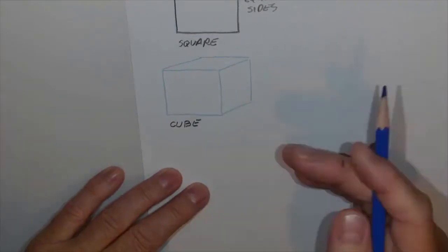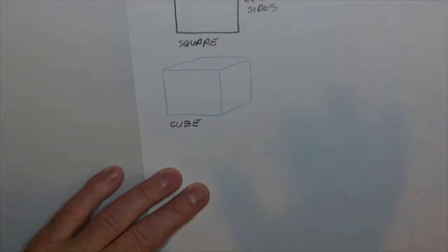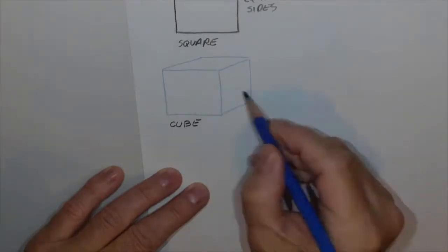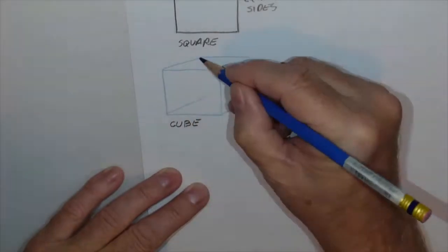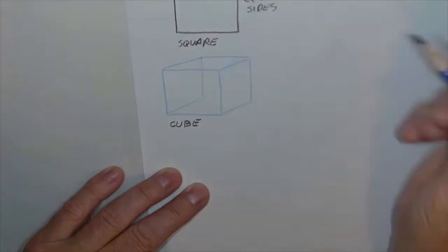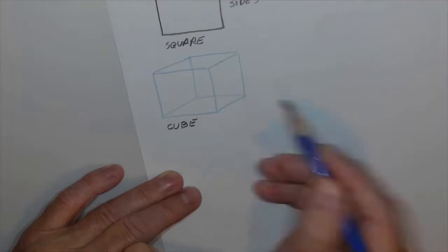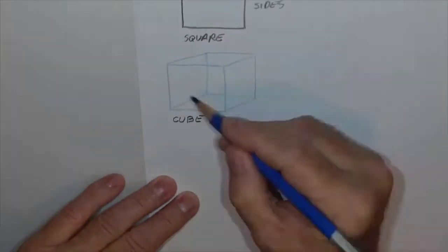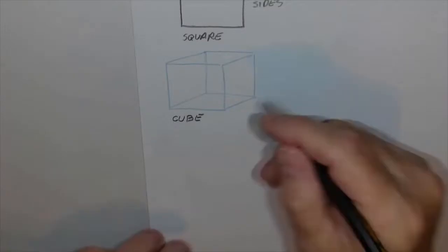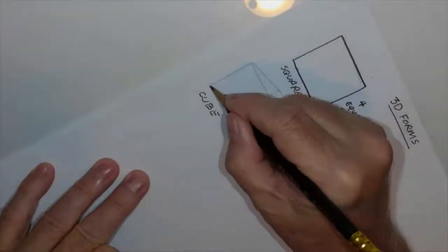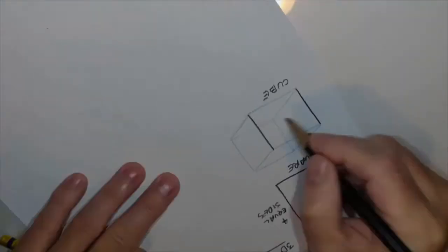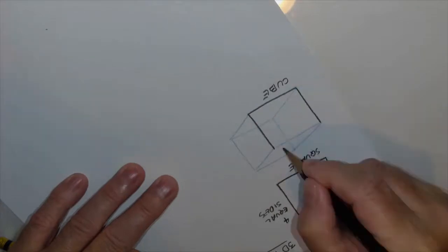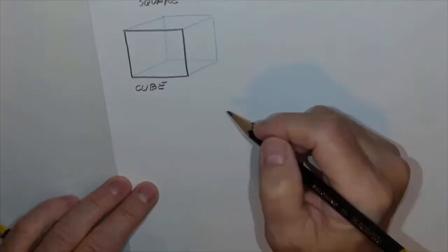In reality, when we're drawing in 3 dimensions, a habit and a process I want us to get into is to complete the drawing as if it's transparent. So I did these lines coming out. I also want to do a line here, and I want it to end where it lines up with a vertical line, and then connect this line over here. So we have a transparent cube. Now, finishing this off, I'm going to do a straight line, a straight line. I'm only going to use a lead pencil on what we would see in this dimension.